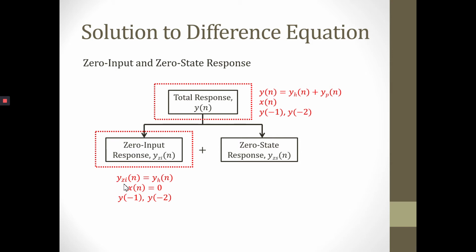The zero input response is equal to the homogeneous solution, where the input is equal to 0 and it depends on the initial conditions y[-1] and y[-2].